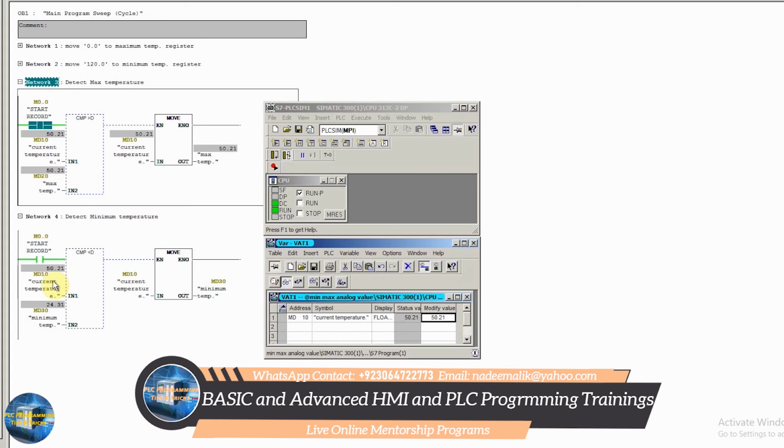As you can see, the current temperature is 50.21 degrees, and as the current temperature is greater than the minimum temperature reading, this time the comparison instruction result remains false and the minimum temperature reading remains as 24.31 degrees. In network number 3, you can see that the maximum temperature data register MD20 is also updated as 50.21 degrees, as the current temperature has increased to 50.21 degrees.